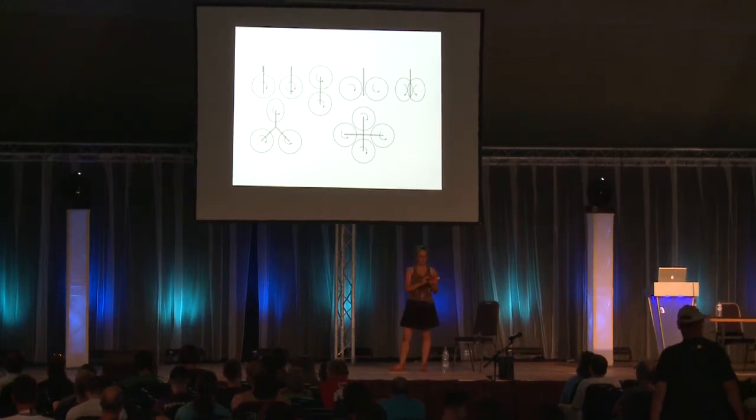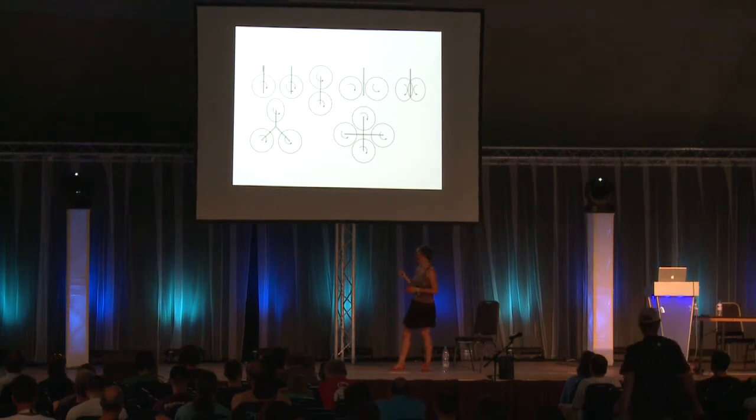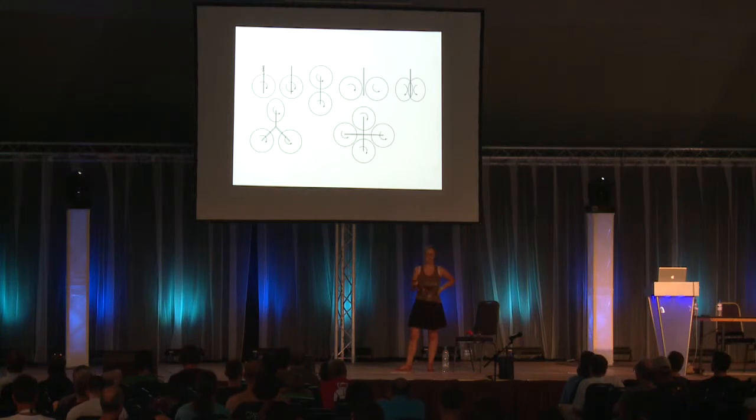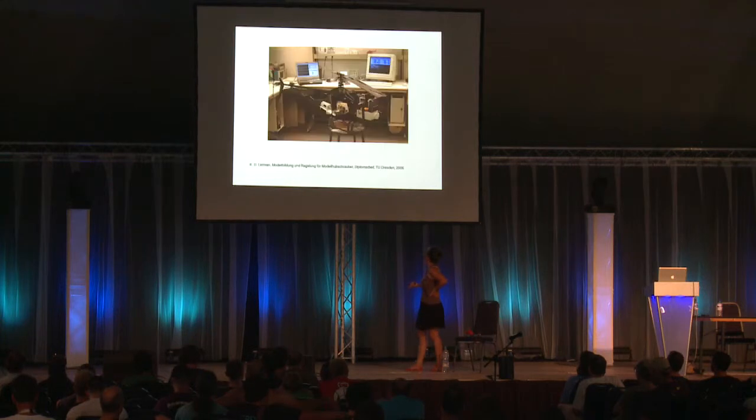The fourth setup is pretty famous for micro-scaled copters. Those are flying in the back here. It would be a quadrocopter, set up like that, where you align them in a kind of cross, but you could also align them in a cross like that, or you could choose 8 rotors or 12 or whatever. The big advantage of a high number of rotors is that if one fails, you have enough left to at least land safely.